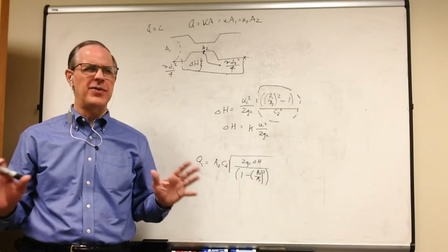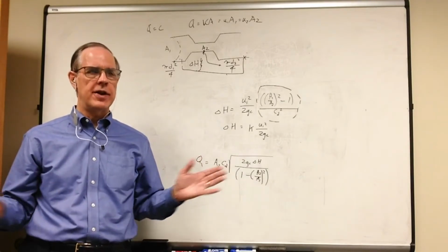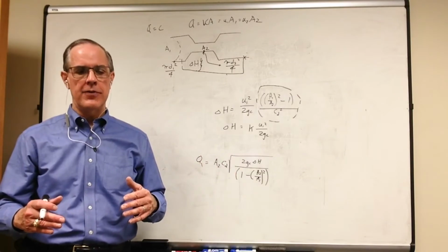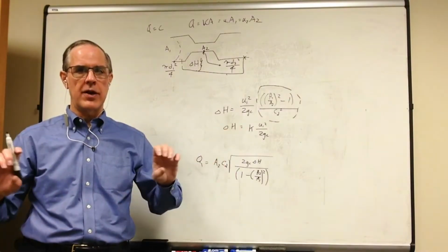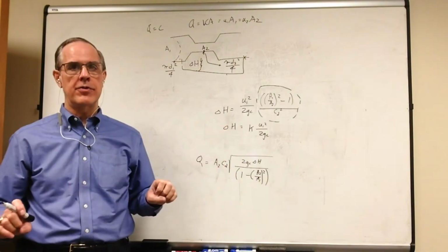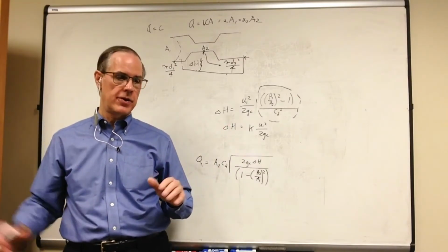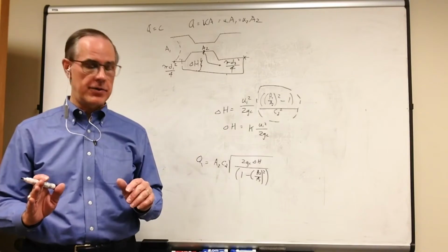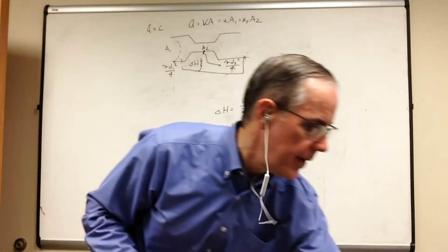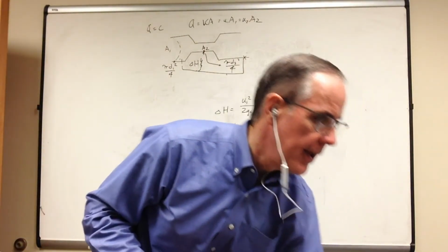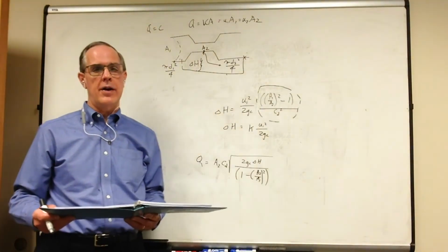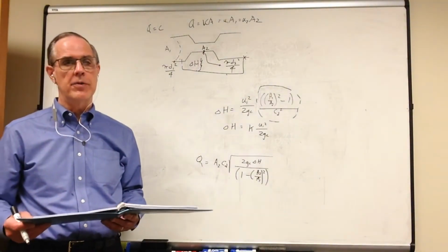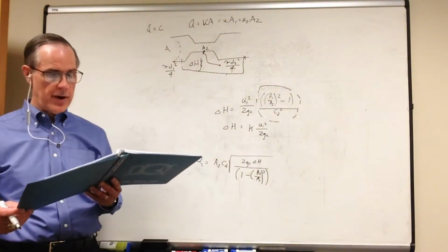Most valves and whatnot have a standard inlet port to them. If you're reducing down or going up to it, that's going to have some additional losses, and they can be put in series. One way of doing that, since I brought that up, we might as well go ahead and do it here, is the equivalent length. Not a subject that gets a lot of press in some fluid mechanics courses. We're going to do it anyway.